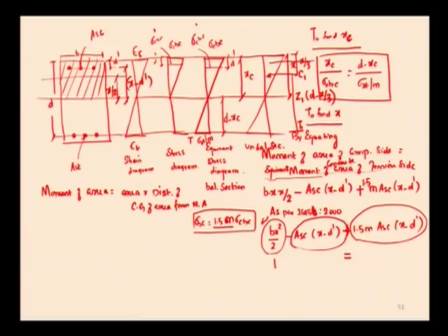And here again C2 be another compressive force which is offered by the compression steel, which is placed at d dash from the topmost extreme fiber, and to balance the force there is another tensile force T2, and the distance between T2 and C2 is again called a lever arm Z2, that is d minus d dash.